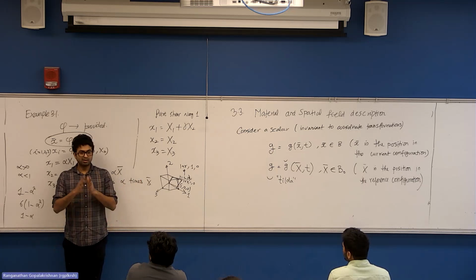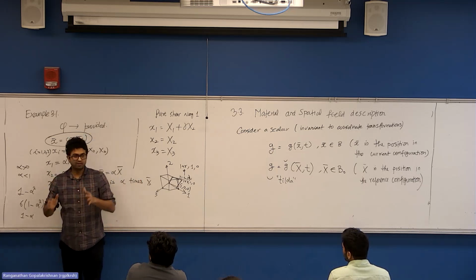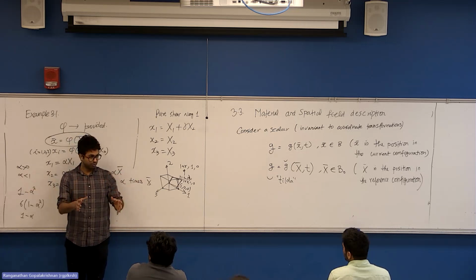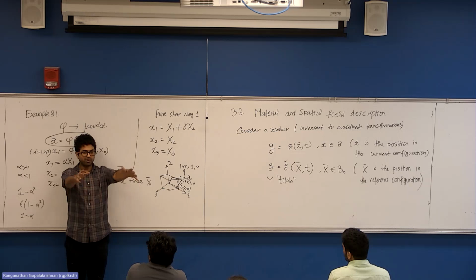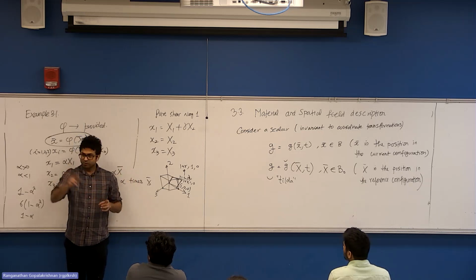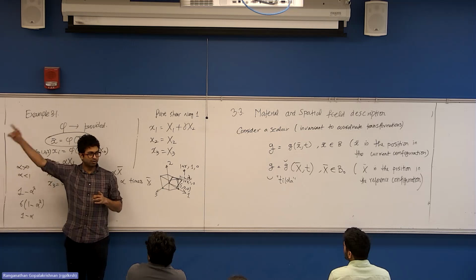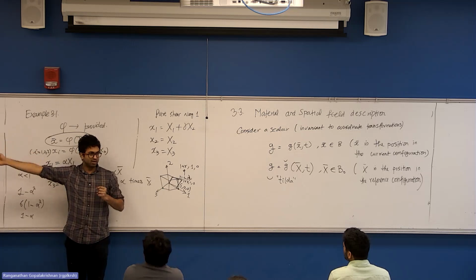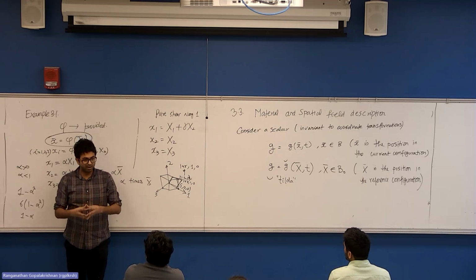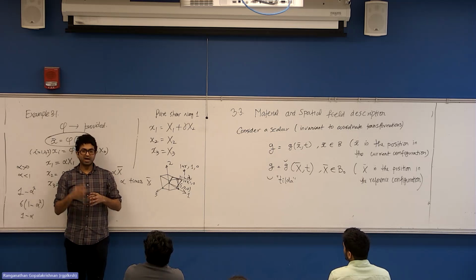If I abandon that Eulerian view, if I abandon my interest in the space and actually get interested about you, about right now we have 7 of you. If I track each of you separately, tonight where you go, tomorrow what is your schedule, etc., that becomes what is called the Lagrangian or material description, wherein you track a bunch of particles and see where they go instead of focusing on where they are.